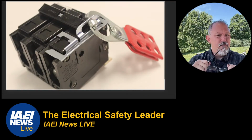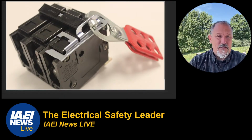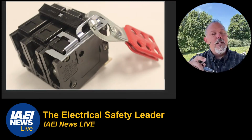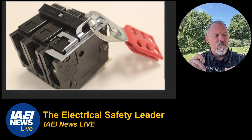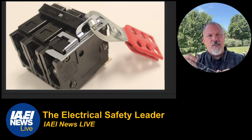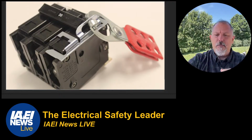A company policy not to open any boxes energized. And a box, I don't know what you mean by box. A panel board could be a box. I mean, it depends on your definition of a box. You can use no contact measurement instruments. So Felix, you've got to be very careful using no contact measurement types of devices. You can use it as a part of the process, but you should always use a proper tester.